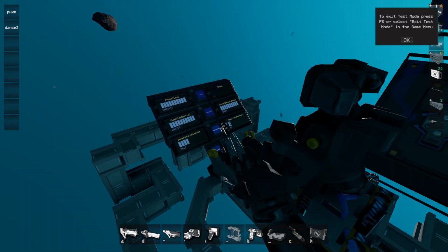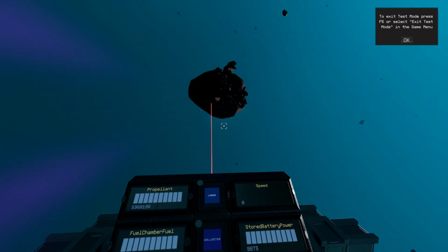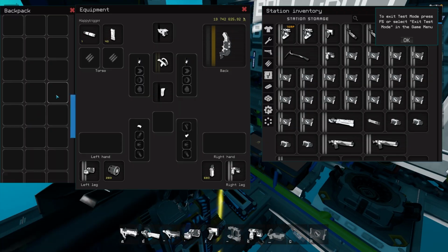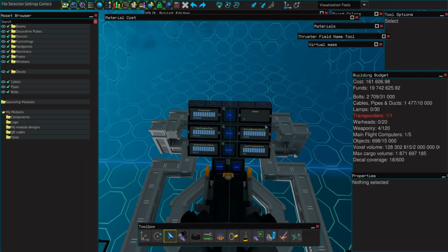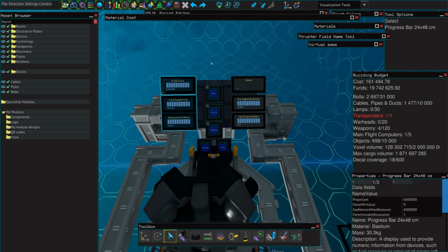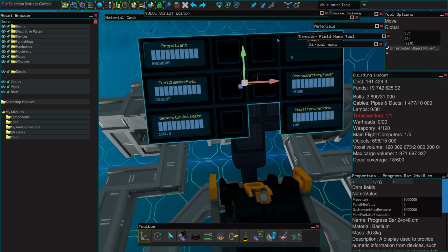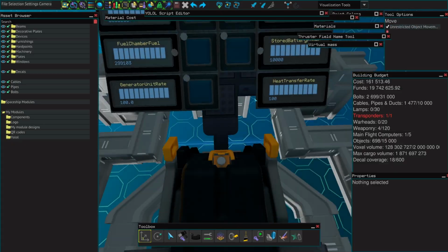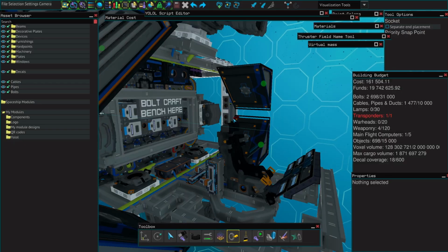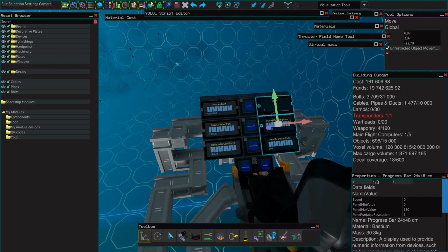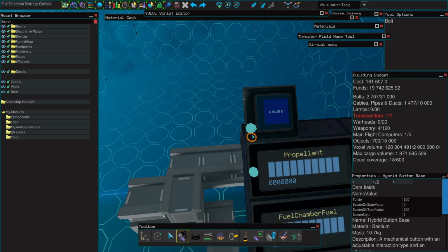Here, what just happened is that the thrusters were not named properly, so one of the reverse thrusters was not turning on correctly. This is because it had one of the same names as the thrusters on the back, and both of them were being fired at the same time. In this case, I used the auto thrusting naming tool in order to fix the problem, which is why you need to be very careful about the thruster names.